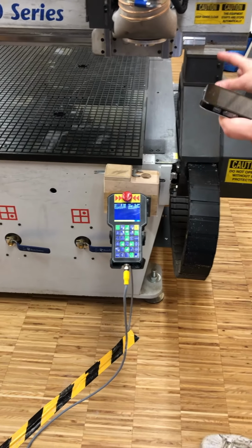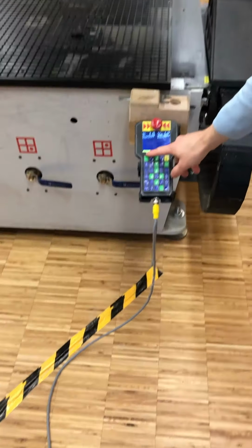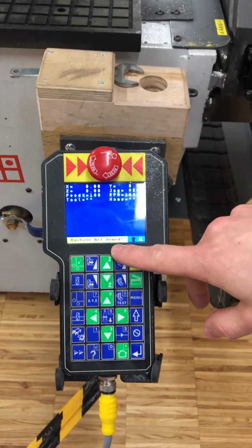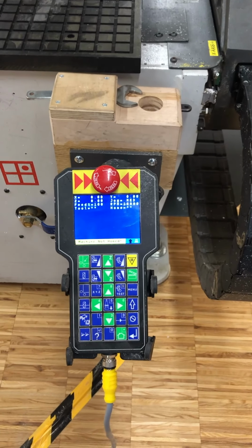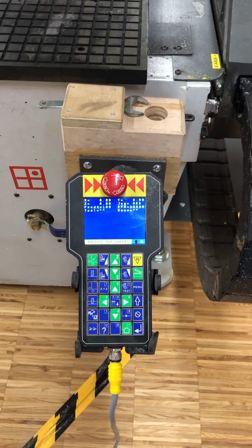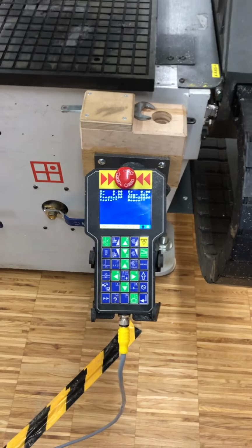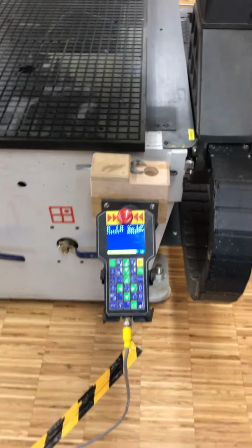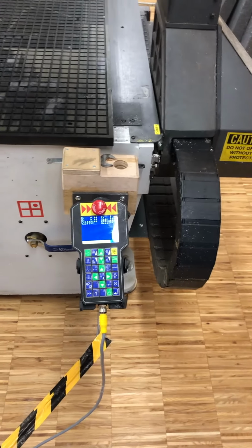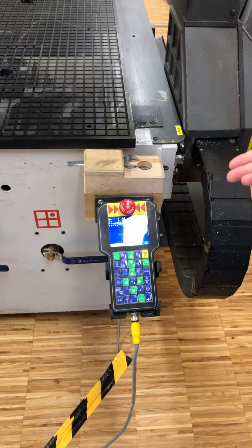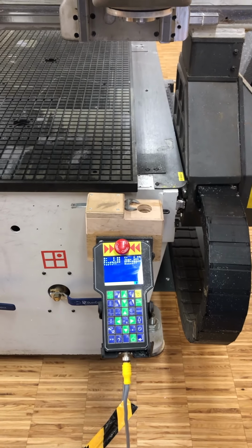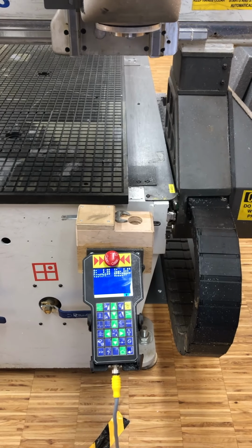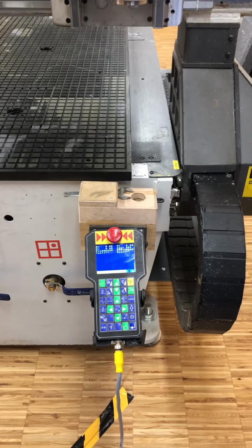When the machine is booted up, there will be a yellow warning sign on the controller which says machine not homed, and that simply means that the machine is booted up, but it doesn't know where it is. We see that it's here around the origin points, but it doesn't know where it is because it has been turned off and the memory has been purged. So we will make sure that it knows where it is. Now that it is positioned here in the origin points, it will be a very short distance for it to home, to find its hard home.